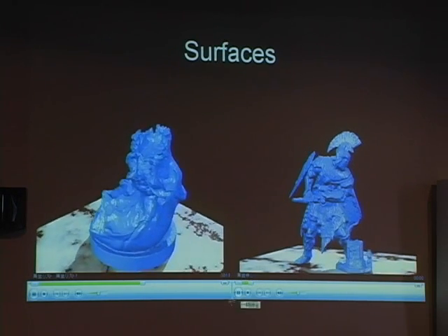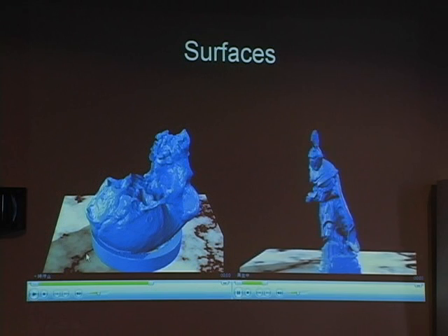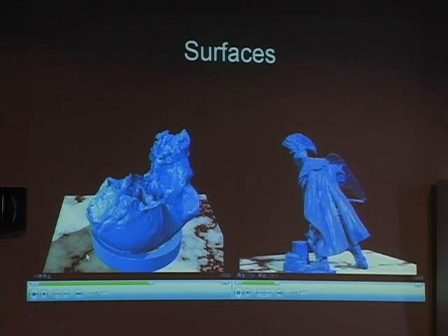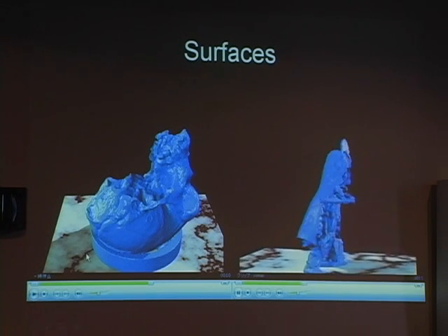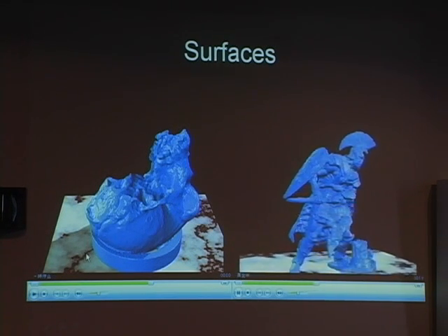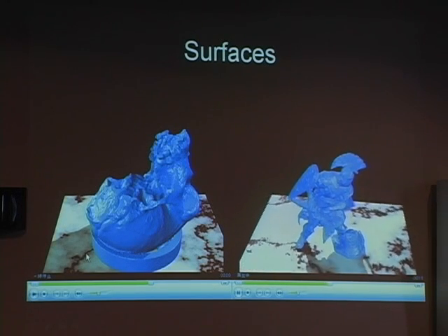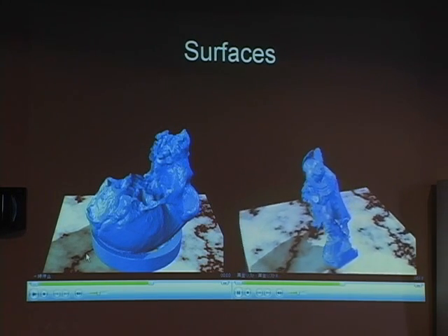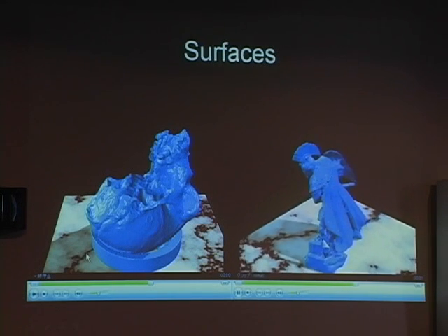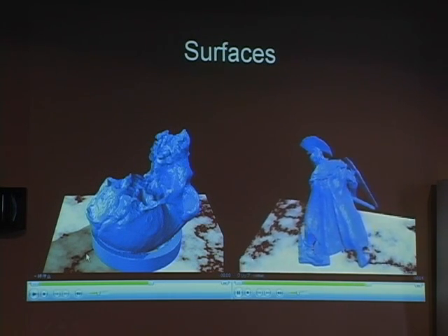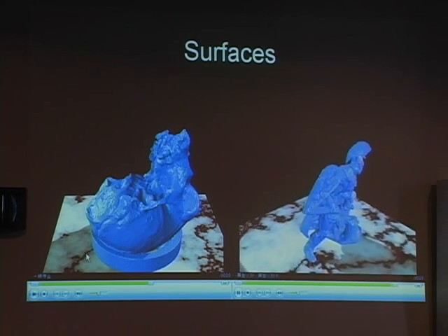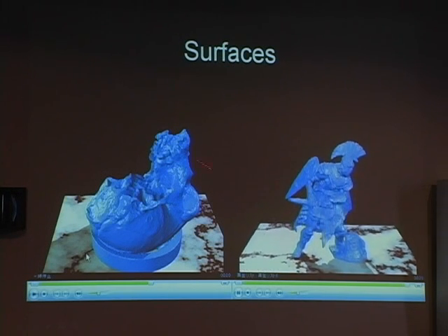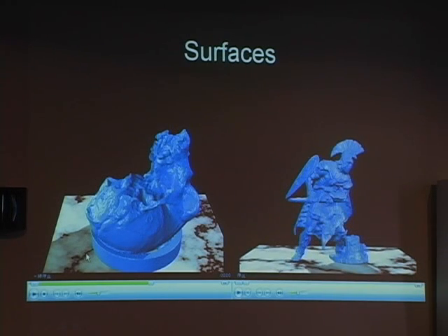And on the right-hand side, this is a kind of massive data set, about 48 high-resolution images. And I guess the reconstruction is almost accurate, except for a few places. For example, here, this is actually a garbage, our whole structure. And this part cannot be reconstructed simply because this is a cape and we're seeing the structure behind it. So there are not many cameras, probably only a single camera looks at the surface. And to do 3D reconstruction, you need at least two cameras to look at the structure. So this is a place where we really couldn't do anything. But for the other parts, I think we did a pretty good job of reconstructing the structure.